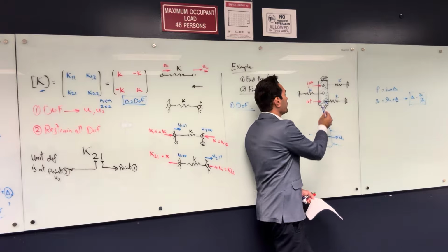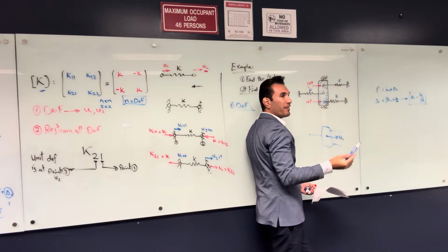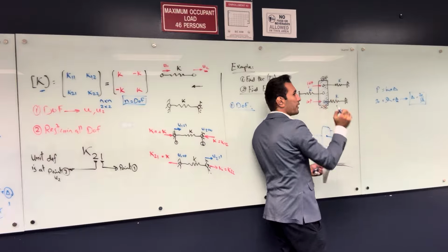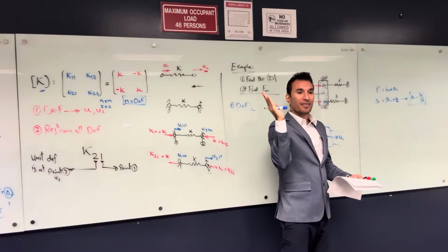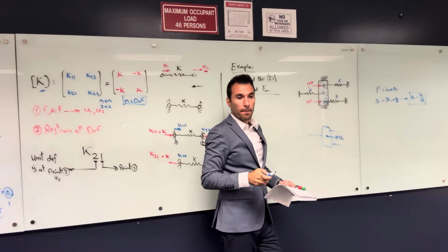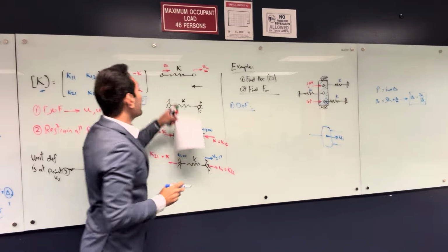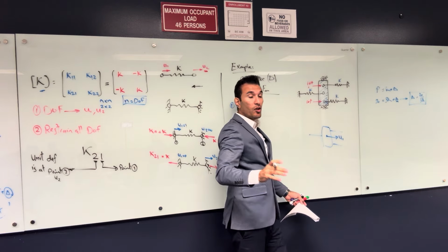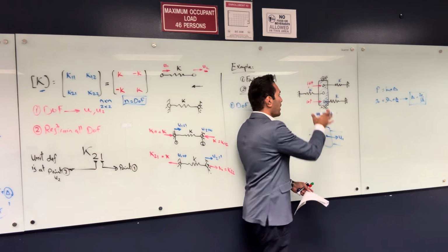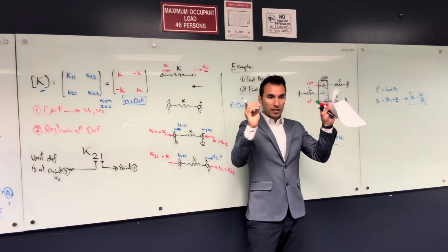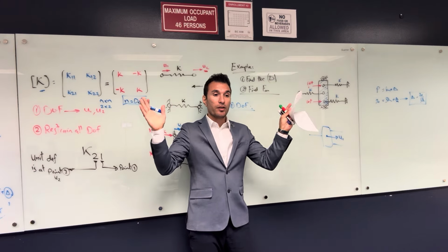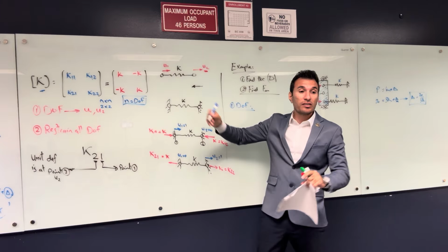Yeah, you can say, oh, it's a 3, I have 1, 2, and 3, but the thing is they are equal to each other. Unless there's something going here, this body can make like this. Now we have 3. Why did that one have 2? This is a member. Right now I'm talking about a structure. If you take this member alone, we are looking at the degrees of freedom if this member is free. So that's what I did here in a member stiffness matrix.